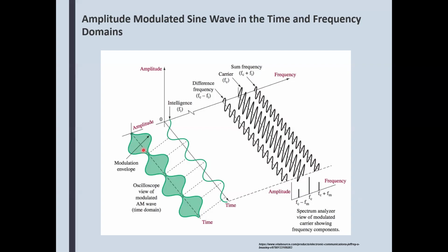So the modulation we want, and this is a good visual here, we don't want any clipping here, and we don't want any clipping here. So we want anywhere between 90 and 95%, and we're fine. So this here looks like it's almost 100% modulated.